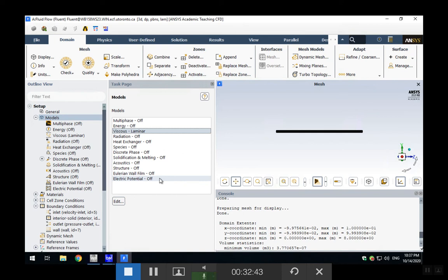So if you are inside the pipe and the Reynolds number is below 2500, it's a laminar flow. If it is above 2500, it's a turbulent flow. And remember, you do not assume anything in the exam. If you want to select laminar in here, you have to explain why. You have to calculate Reynolds number and show me it is actually laminar.